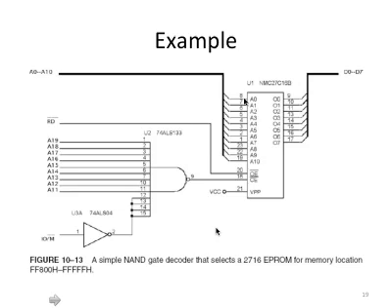So let's see what will happen if the microprocessor is going to read this address, FF800. If you write this number in binary, you can easily find that for this address, the upper 9 bits, the most significant 9 bits, are all ones.